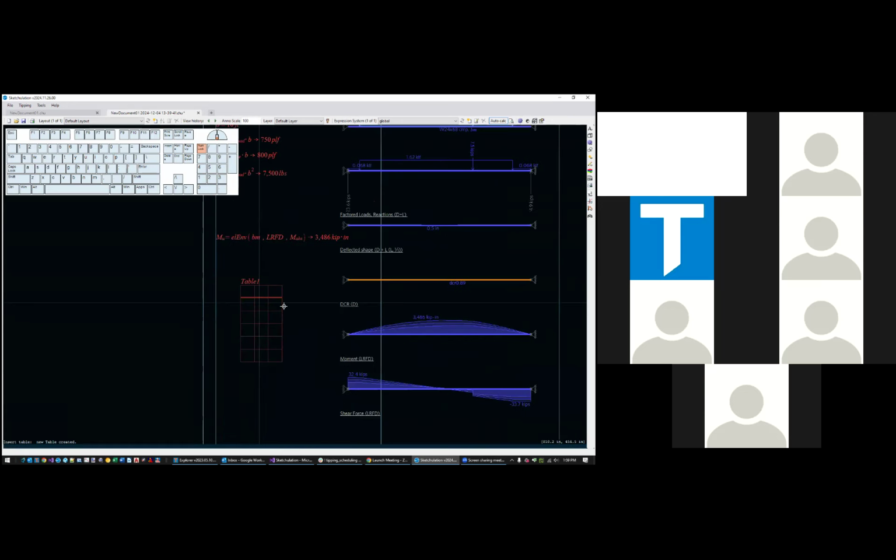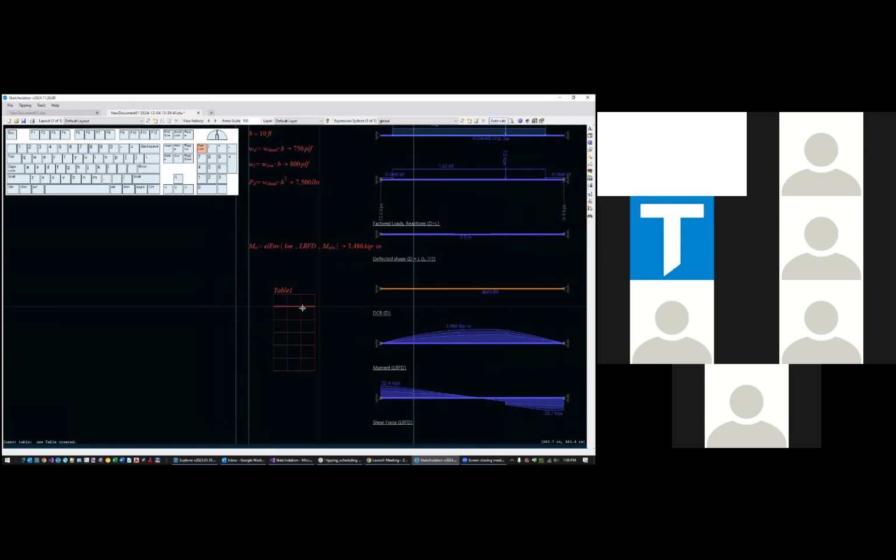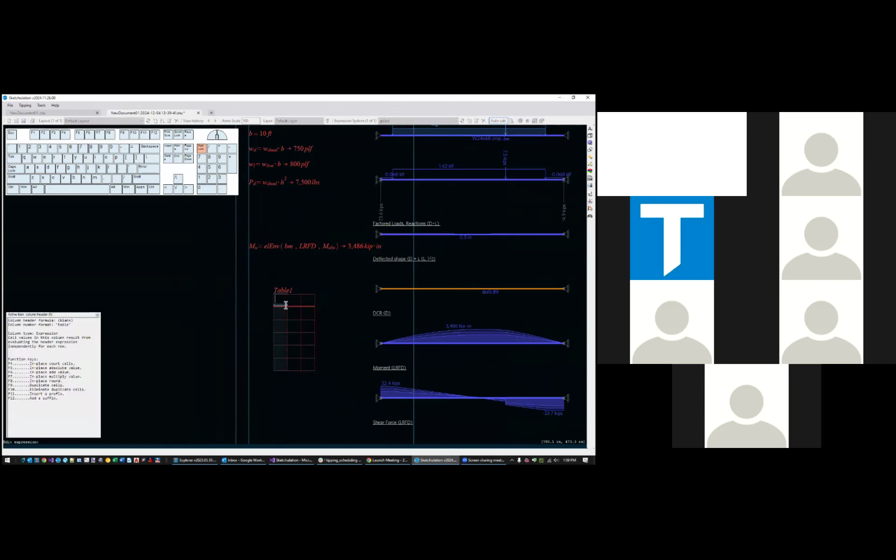And why don't you tell me exactly what you have. Let's say, for all combinations, we need the maximum moment and shear, for example, and deflection. Okay, so there's a couple different ways to do this, but if you wanted to see them here, we would make a column here. We would need to make sure that this is the right name. So let's say 1.2D plus, and there's some spaces in here.